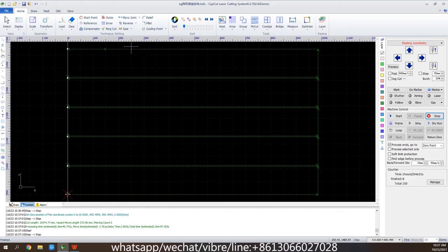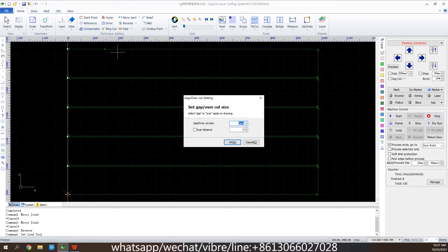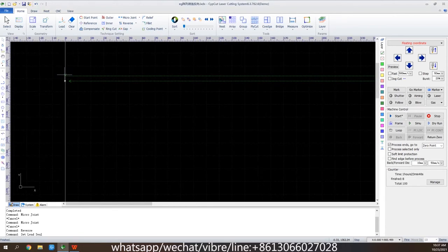Down below, this is the gap feature. In the drop-down menu, we can see the gap. Select the graphic and click it when we need to set a gap at the end of the cutting path. Here is the gap. On the control rail, we can seal the gap if we don't want it anymore. There are also overcut and multi-cut. Overcut is for making sure the whole part was machined, and multi-cut is for an obvious marking.